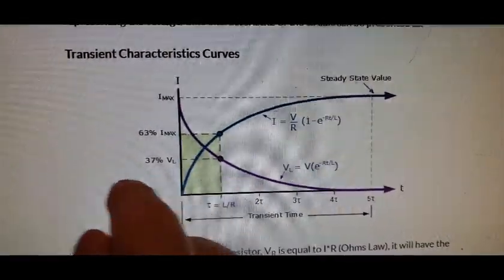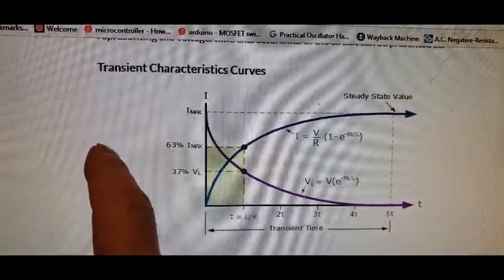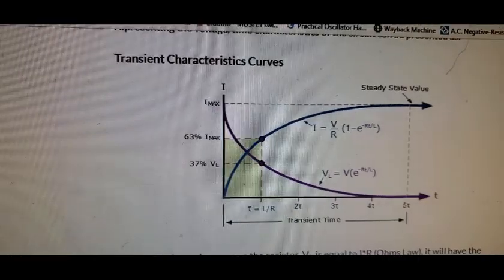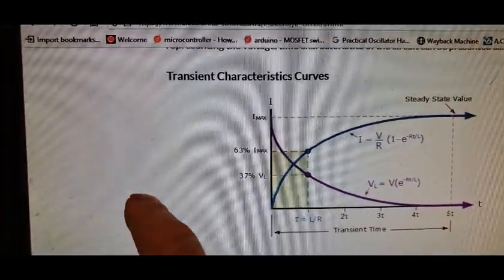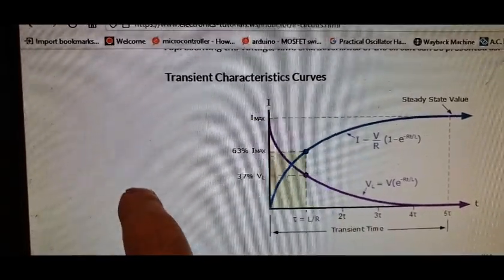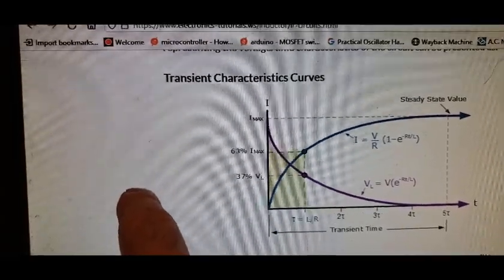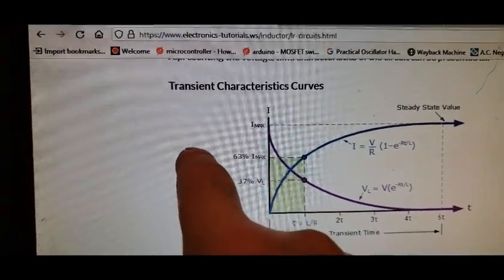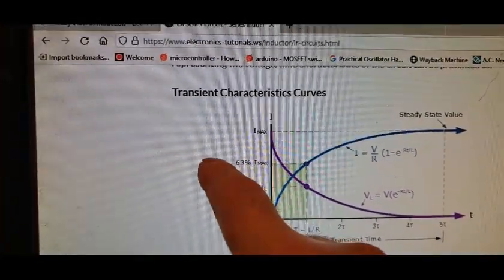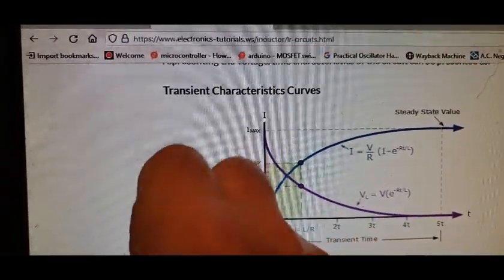So when you discharge a cap into a coil, what do you have? You have an LC tank circuit, right? Yes. And your capacitor will discharge into the coil and go to 0. Now the coil is filled with current. The current discharges in the opposite way, leading to a voltage driving the cap negative, and then it goes back up. And there's a particular frequency at which the cap and the coil oscillate.